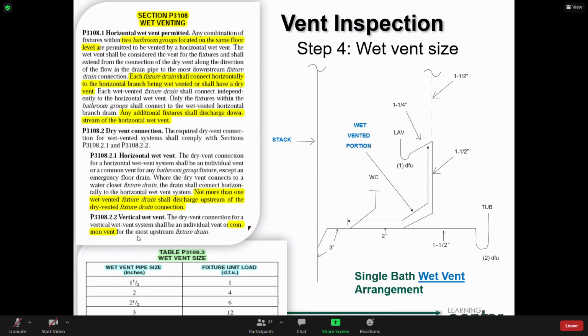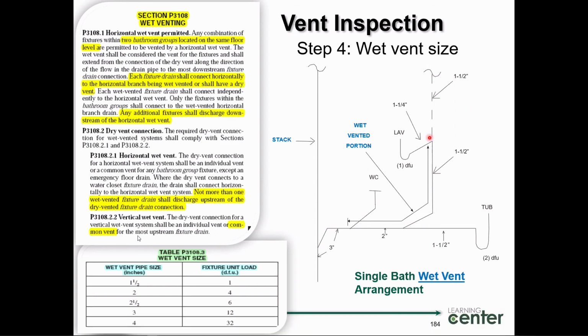So in order to size our dry vent, we need to take half the diameter of the largest drain served. If that's 3-inch pipe, half of 3 inches is 1.5 inches. And then I do a check and I say, remember, the smallest dry vent I can have is 1.25 inches, and this in fact is more than 1.25 inches, so it works, right? Does that make sense?